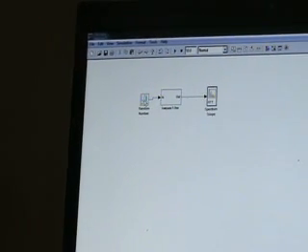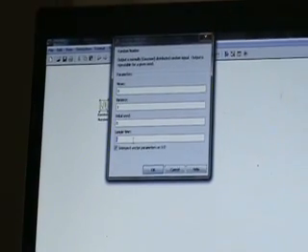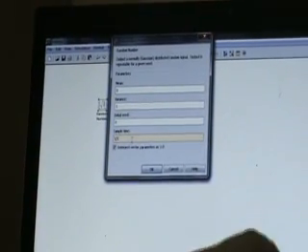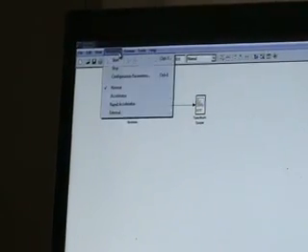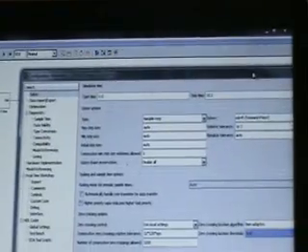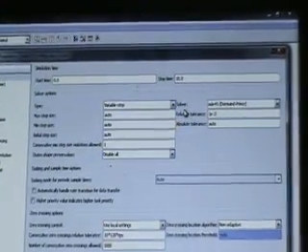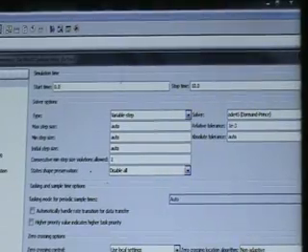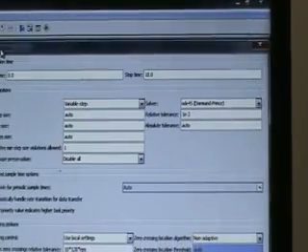Now this random number generator is a continuous signal. First we need to sample the signal by giving the sampling time. Then in the simulation we have configuration parameters. As the random number generator gives continuous input, we need to change that to discrete, as the digital filter which we have designed here is a discrete input filter.